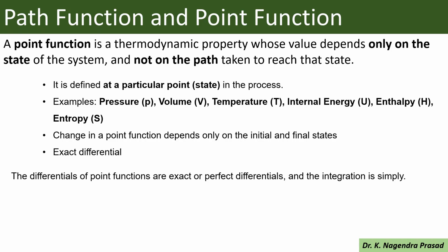So remember all these properties. They are very important from the objective point of view. Change in a point function depends only on the initial and final state, and these point functions are exact differentials. For example, V2 minus V1, or T2 minus T1, or P2 minus P1, U2 minus U1.